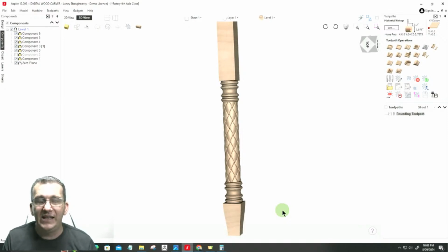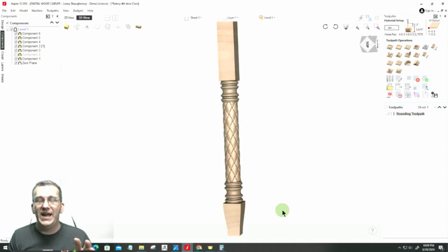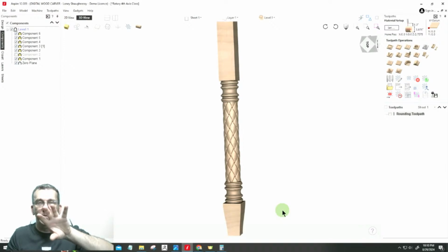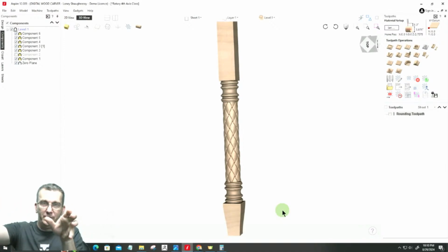Now, if it is set up like a true rotary axis where it's the A-axis, your A-axis typically in your controller software runs by steps per degree, 0 to 360, and degrees per minute. Basically, to go from point A to B, my spindle is going to turn, let's say, from 0 to 45 degrees during that motion, right?